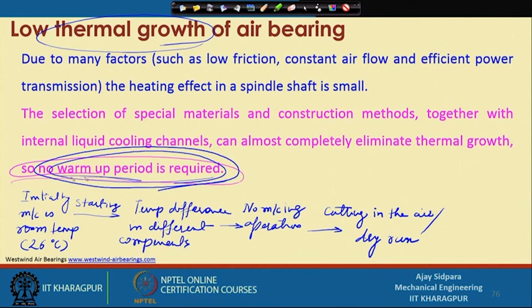So, you have to provide some warm-up period so that there is full thermal growth of all the components, and there should not be any further problem during machining. Whatever defect you are getting, whatever the change from the original position to the required position, that will remain constant, because you have already given the warm-up period. If you do not give a warm-up period, your required dimension and the original dimension will keep continuously changing till it reaches this location.